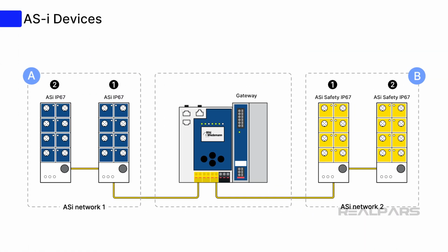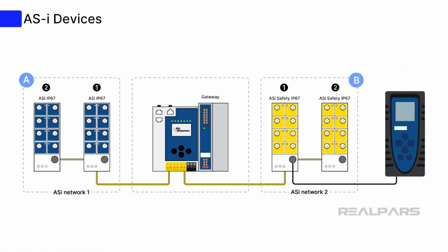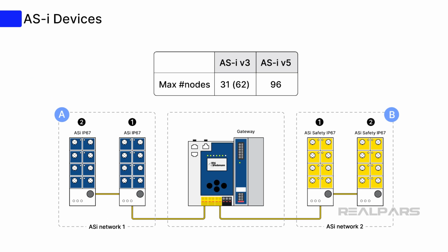The ASi master, or an ASi address programming device, is used to perform ASi addressing on each device. This address is used to identify individual nodes in the ASi network, and as mentioned previously, addresses cannot be repeated on a single segment. The ASi master version determines the range of addresses possible for segments connected to the ASi master. ASi addressing is critical because if the addresses of two ASi nodes are swapped, the I/O will not be assigned appropriately in the control system's data table.